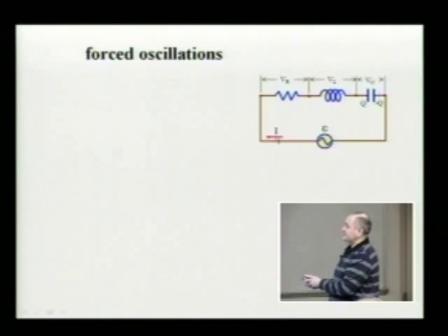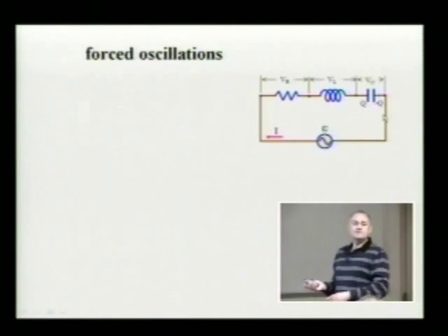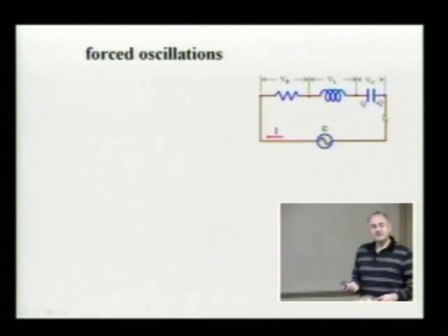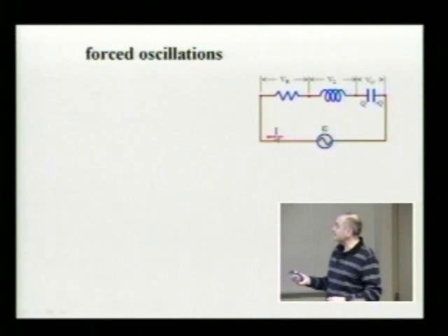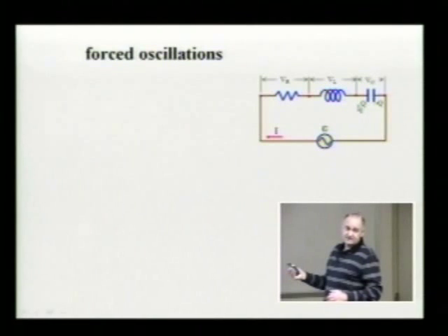In order to have this current equal to the rate at which the capacitor is being charged, consistently, if I mark current that way, I should put Q on the left-hand side. So current I should flow toward the plate which has charge Q, so that the current is equal to the time derivative of the charge on the capacitor.